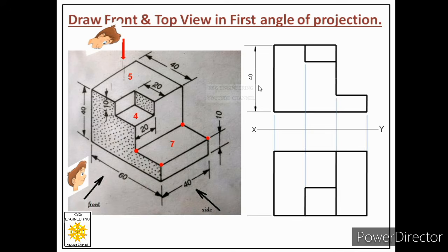After that, let us place its width. So how much is the width? Width is 40. So width is visible here. So it means from these 2 points, we will draw continuous thin lines after leaving 1 millimeter gap. And from the object line, leave 10 millimeter gap and draw the dimension line. So this is the width of the object.